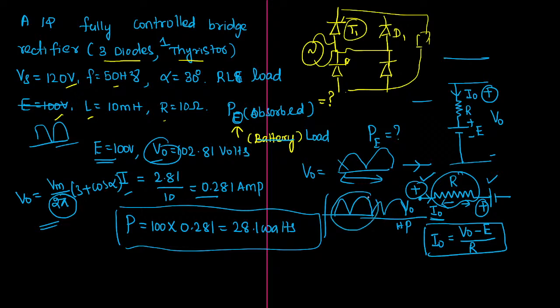For each and every 360 degree this waveform will get repeated. So you have to consider the 360 degree. Suppose if the waveform will be like this, first 180 degree, whatever the waveform that I am observing, same waveform will be in the next 180. Same next waveform will be next 180. When you are observing the same pattern for each and every 180 degree, then the duration of the cycle will be 180 only.